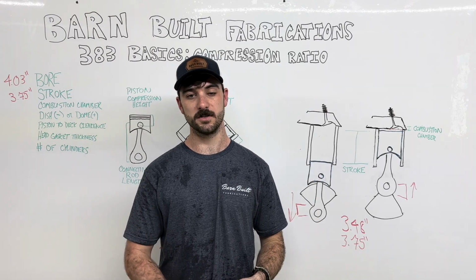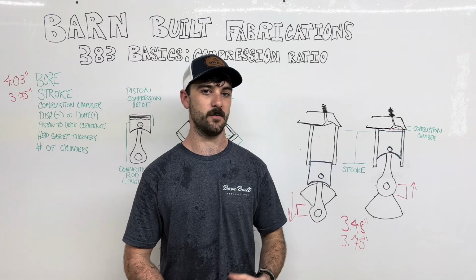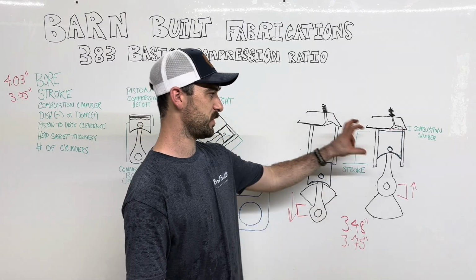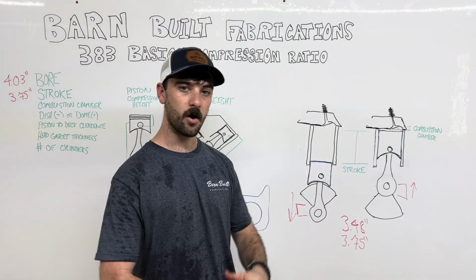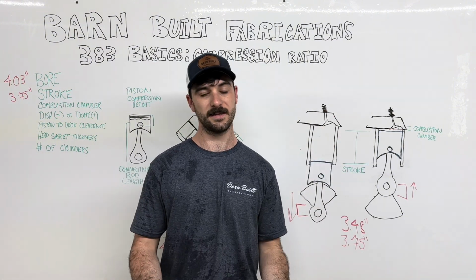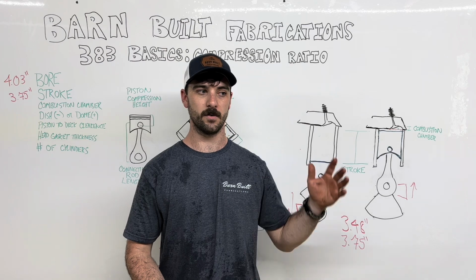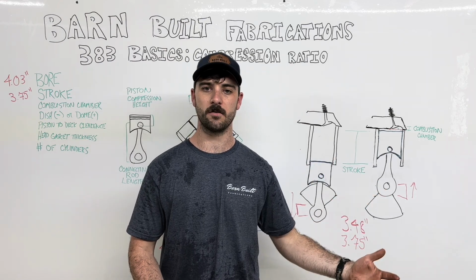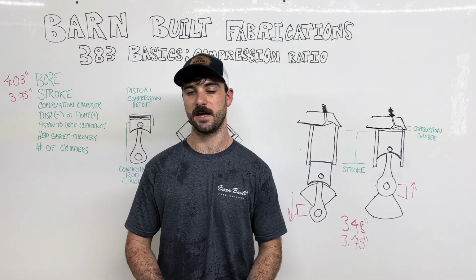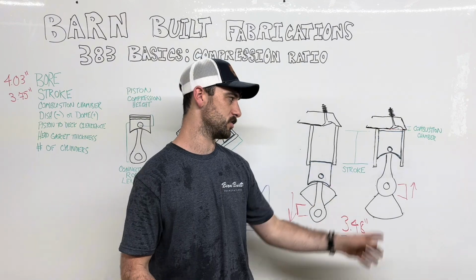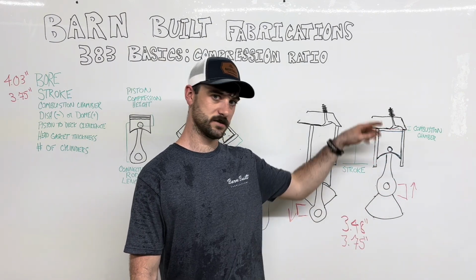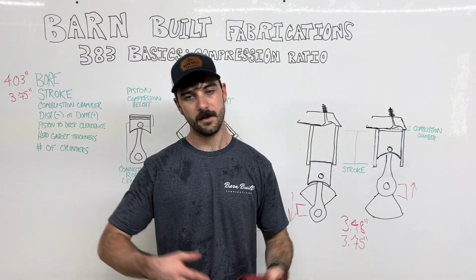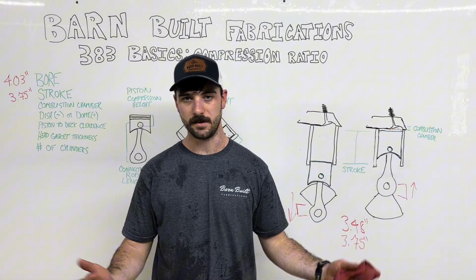It does it very violently and abruptly, and whenever that happens, it rocks your pistons, your rings, your connecting rods, your bearings, all your valves. All the components of your engine take a beating. If that persists for a long period of time, it will cause mechanical failure in your components. You crack a piston, you could break a connecting rod, destroy your bearings, tool up a valve, all sorts of things, you name it.